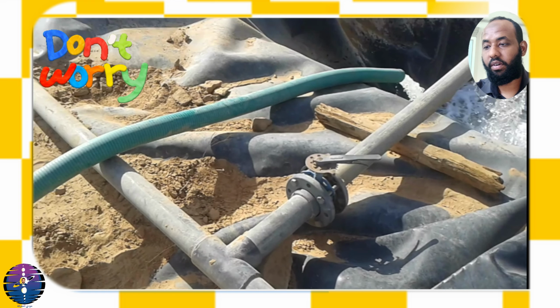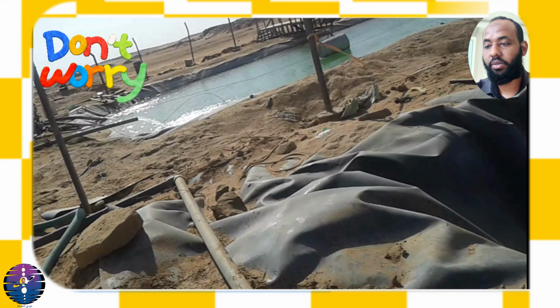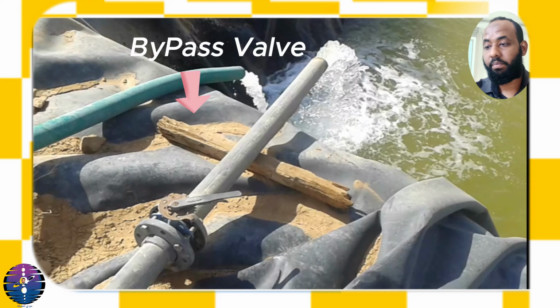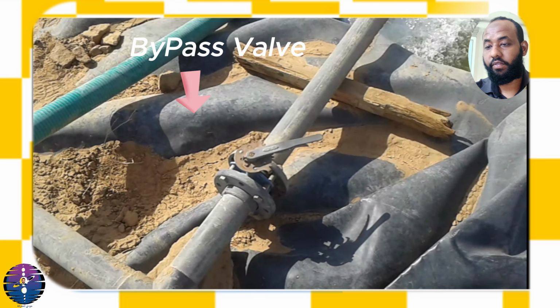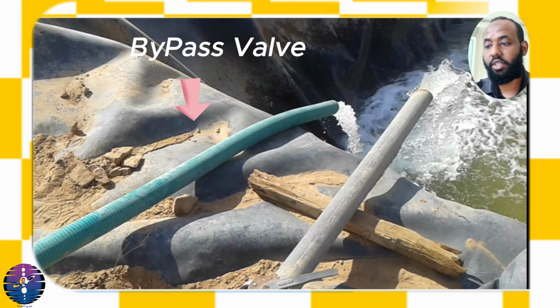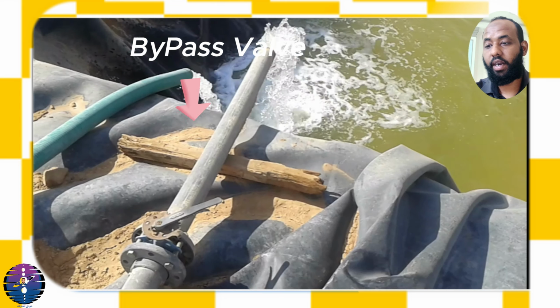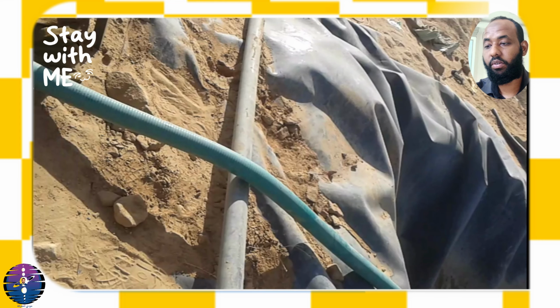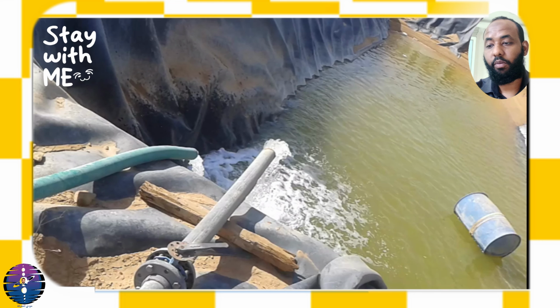We control the amount of solution flowing to the absorption columns using the bypass valve handle. If we want a large amount of gold cyanide solution to flow into the columns, we gradually close the bypass valve. If we want less solution, we increase the opening of the bypass valve, reducing the amount of solution flowing